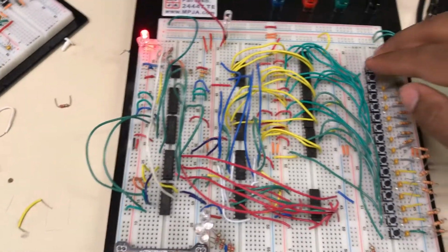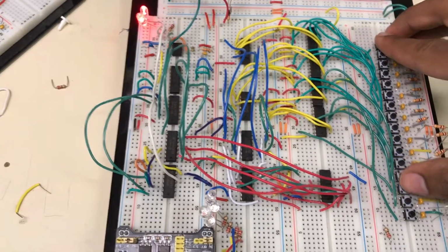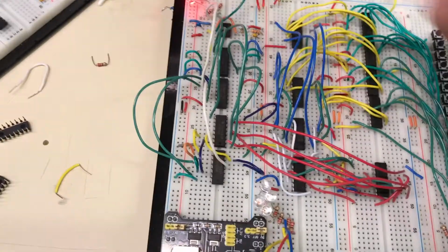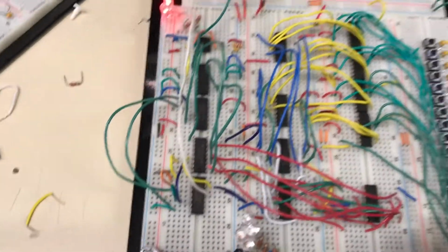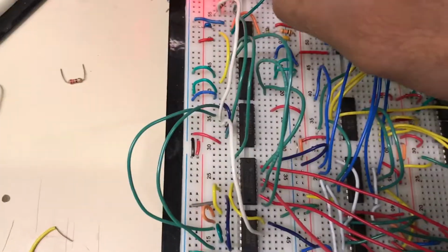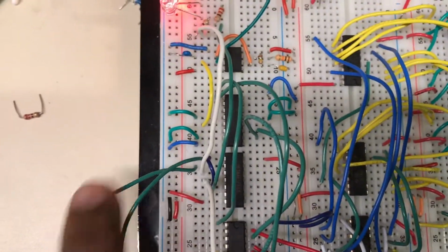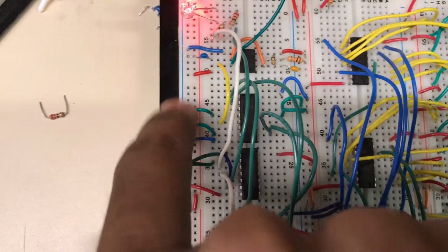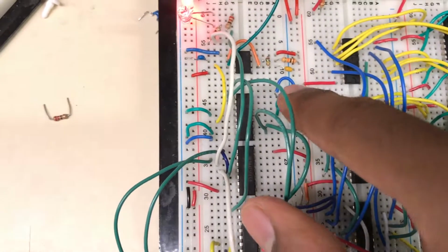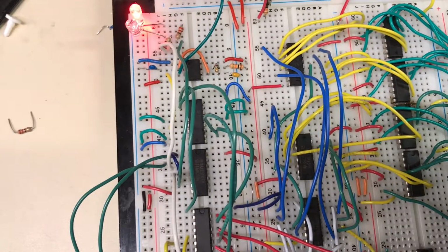So I've gone ahead and implemented the comparator, and when I set both equal to 0, you see that both lights are red, and when I set the floor input to 15, I press 15 here, just the up button is red. So for the sake of testing, I have grounded all the inputs for the elevator. This means that the circuit thinks that the elevator is on floor 0.